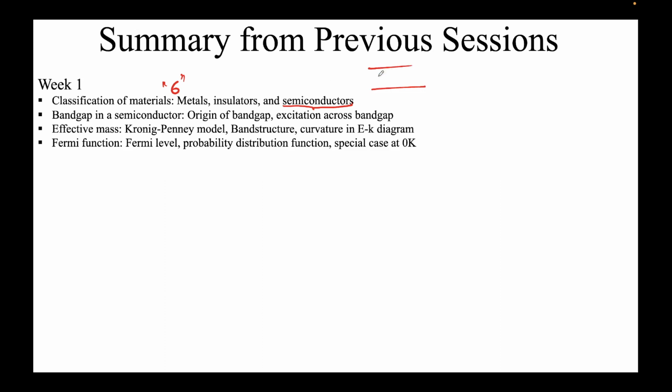That happens when, let's say, you bring a huge amount of atoms close together and their orbitals overlap. Rather than having distinct energy states, they split into bands of energy states. These are still energy states, but they are so close together they appear as a continuum, and we distinctly see a gap between these two bands. So above EC, electrons can be there, below EV, electrons can be there, but in between there can be no electrons. This is the forbidden energy gap.